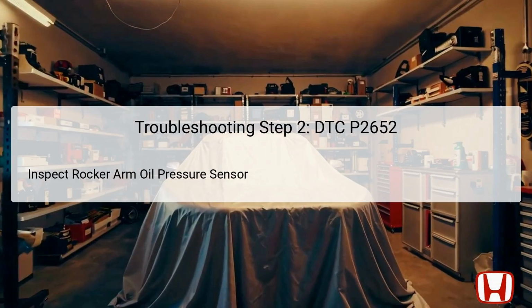Ensure that the sensor is securely fastened and correctly torqued where it attaches to the oil control valve. This inspection is pivotal as it sets the stage for testing oil pressure readings accurately during subsequent steps. In the third troubleshooting step, the rocker arm oil control valve will be inspected for functionality.